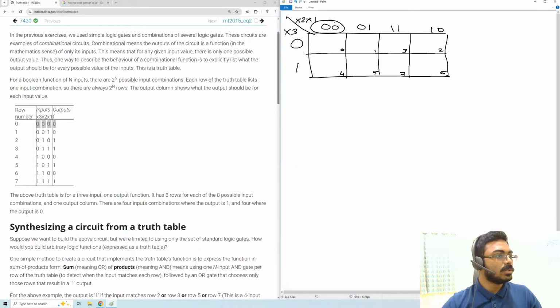So we don't write 0, 0, 0, 1 and then 1, 0 here. We write 1, 0 at the farthest because we only want a 1 bit change here. It's like 0, 0, 0, 1, we only have this bit changing. From 0, 1 to 1, 1, we only have this bit changing. From 1, 1 to 1, 0, we only have this bit changing. If I write 0, 1 and then 1, 0, we have 2 bits changing. So we don't want that. This is called gray code. So when there's only 1 bit changing, if we group them, it creates a combinational logic in that sense that